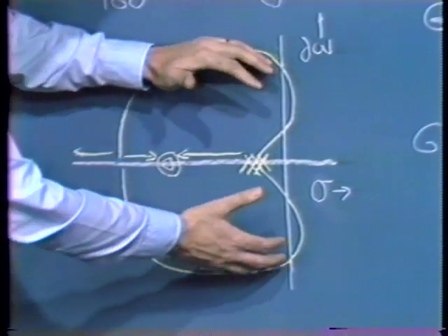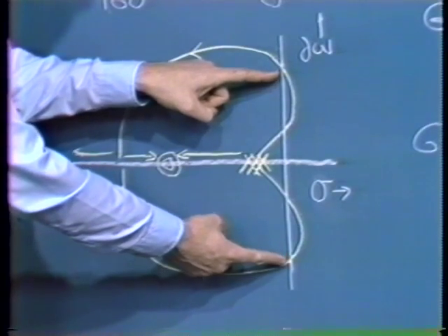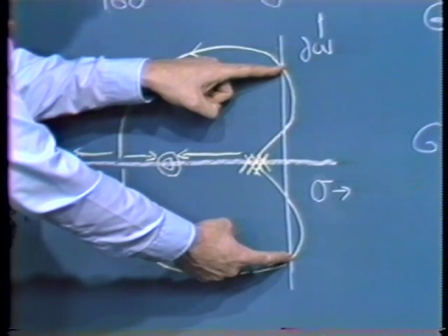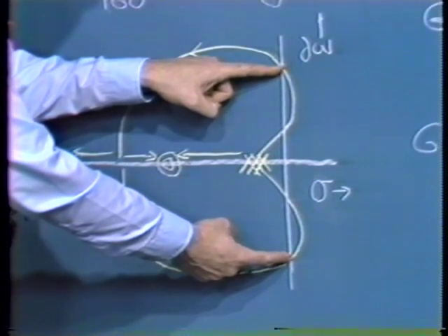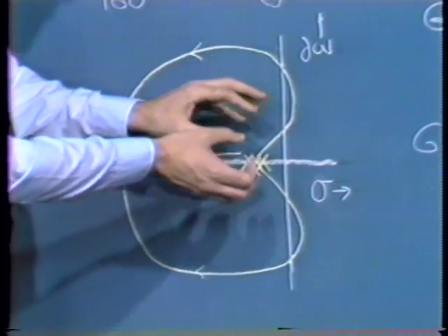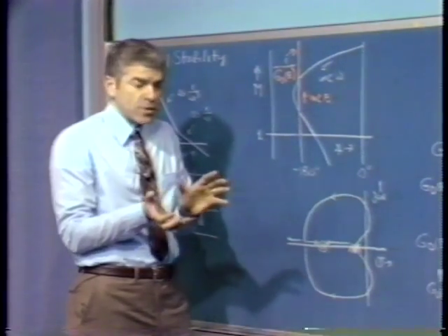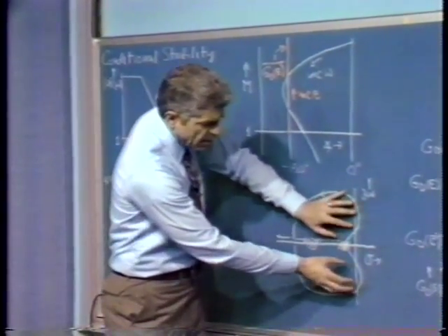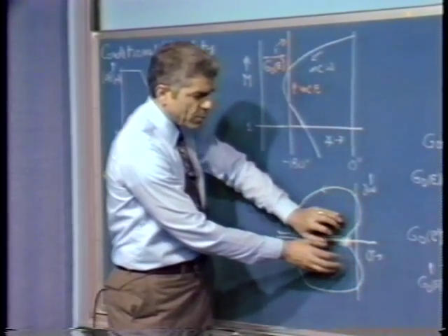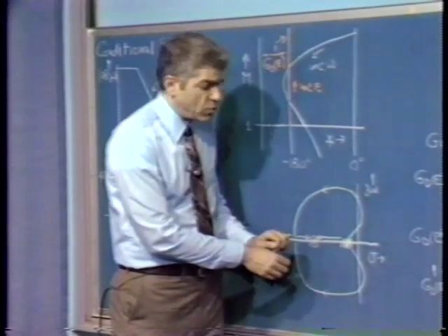The branches move back. For some sufficiently large amplitude at the input to the nonlinearity, we have a pair of complex conjugate poles on the imaginary axis. There's a potential for oscillation. As the amplitude at the input to the nonlinearity is further increased, again we'd get a lower A0 F0 product, since the gain of the nonlinear element in the describing function sense would drop.